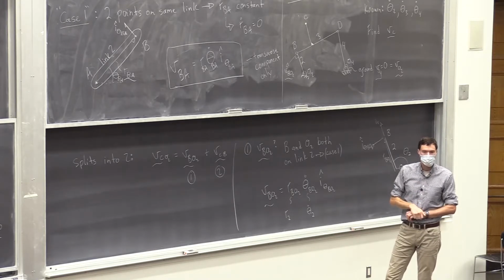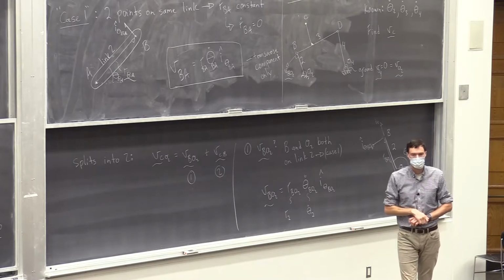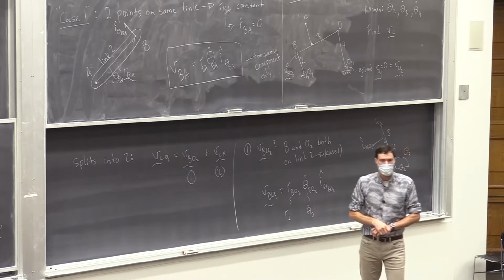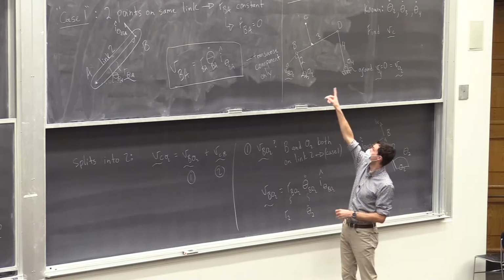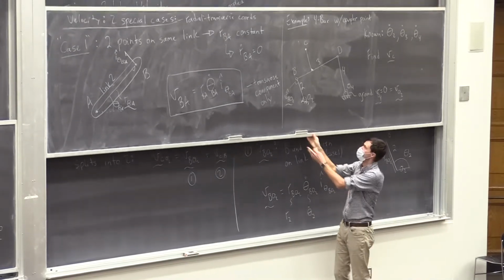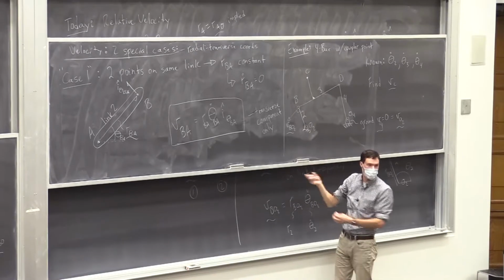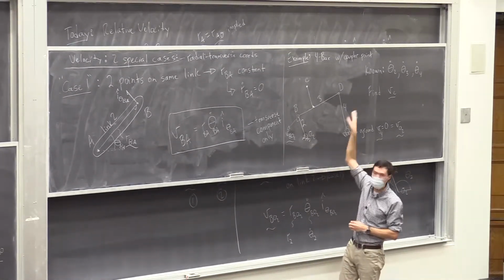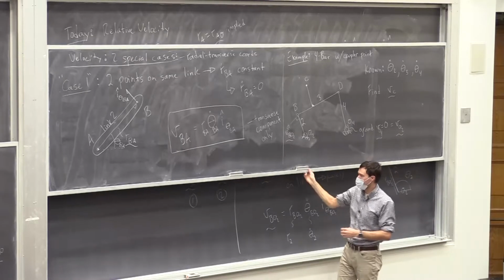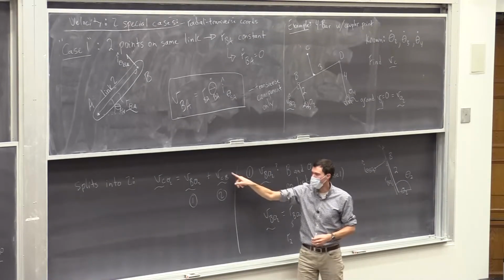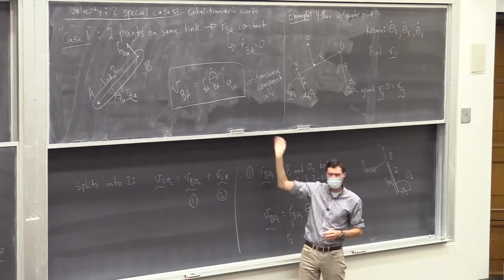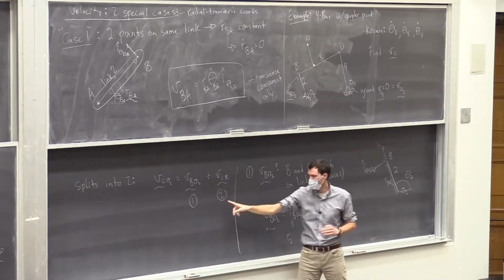Could we expand this to go through, instead of just going through B or just going through D, could we go through B, F, C, and...? Yeah, great question. This mechanism just required one step, going through B first, and then we get to C. If it was a more complicated linkage, if you had a 5 bar and you needed to go through another point, you just make this equation longer. Just add more relative points on. Yeah, and we'll see examples of that later. Let's move on to our second step and maybe answer if there are other questions.